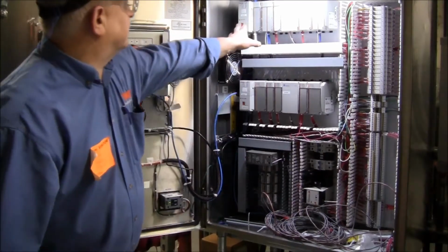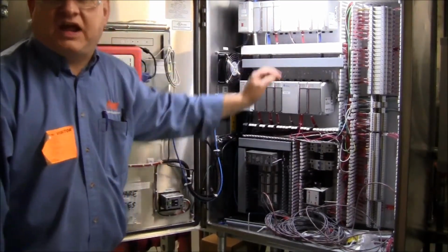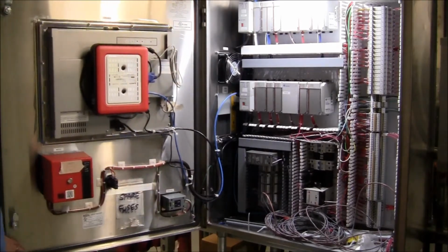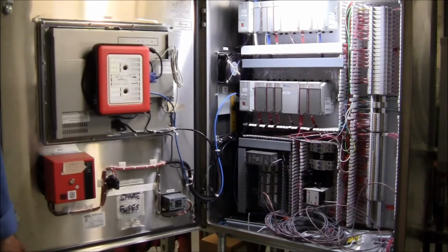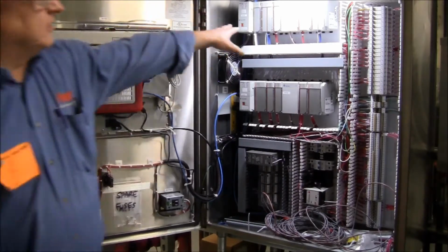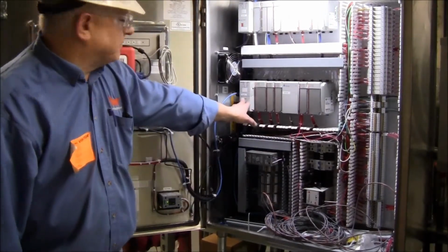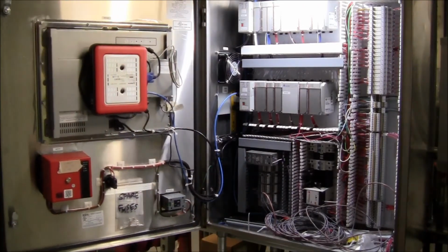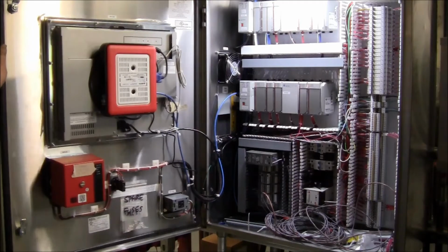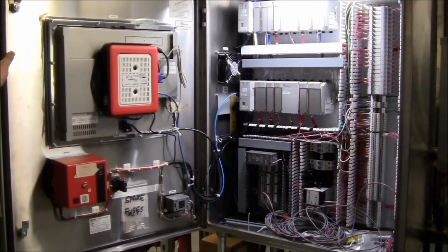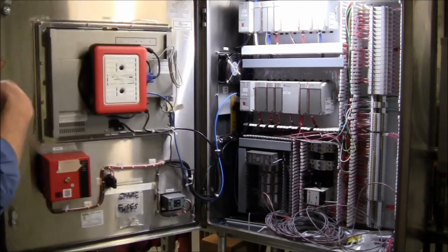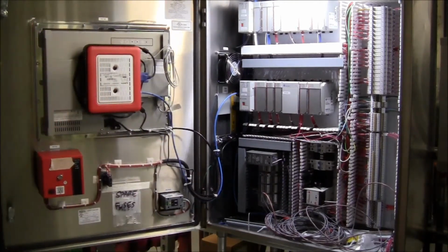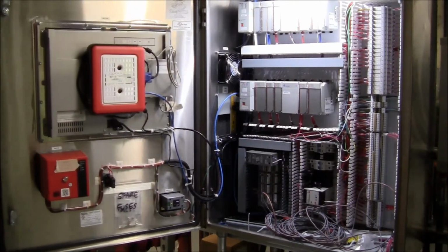So you'll also see the term CCS. That stands for Combustion Control System. That's what controls the air-to-fuel firing rate of the boiler. This actually runs the boiler. There's another system called BMS, which stands for Burner Management System. And that is a separate system altogether, and all it does is manage the safety of the burner. So that has limit switches, there's all kinds of devices that all have to be met in order for